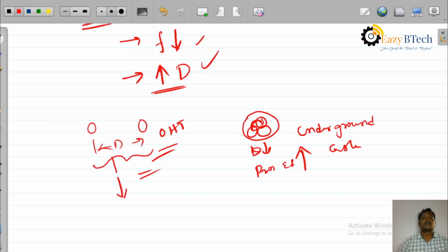This is the way the proximity effect is there in the conductors. Basically, it is due to current flowing in the other conductor. The flux linkage in half of the portion of the conductor is called proximity effect. This proximity effect is less in the overhead transmission system and more in underground cables.